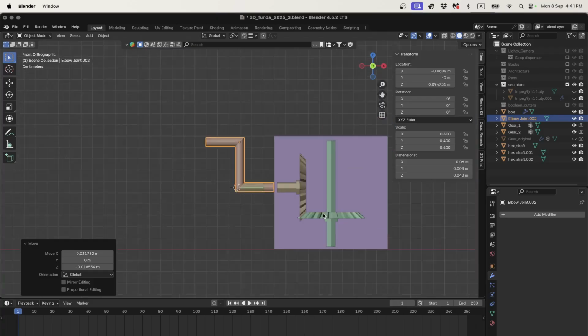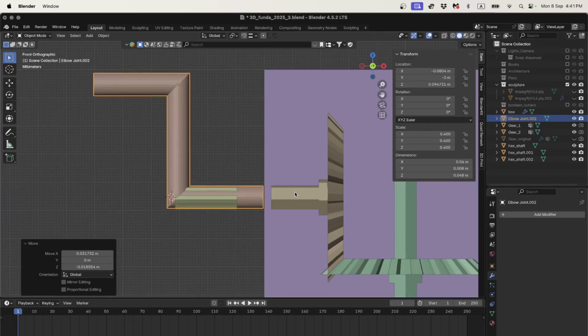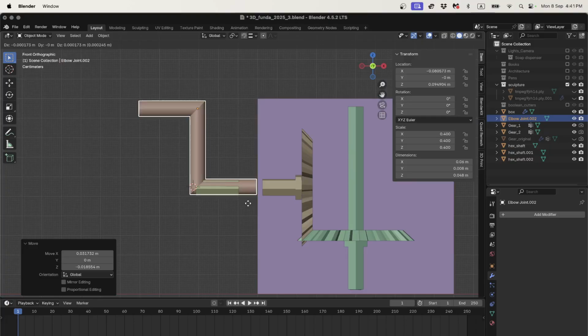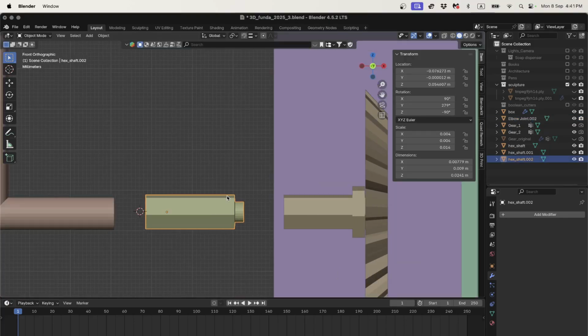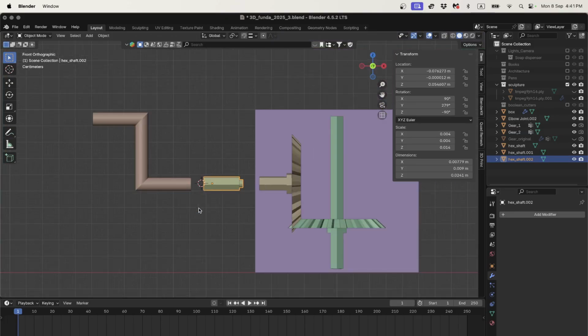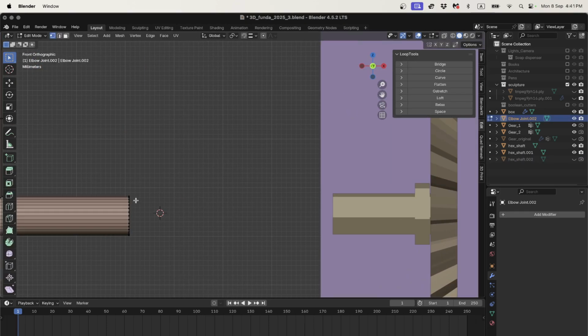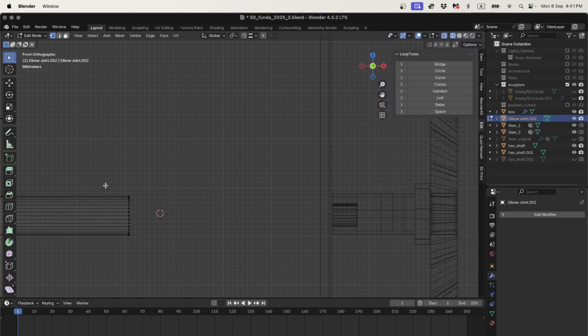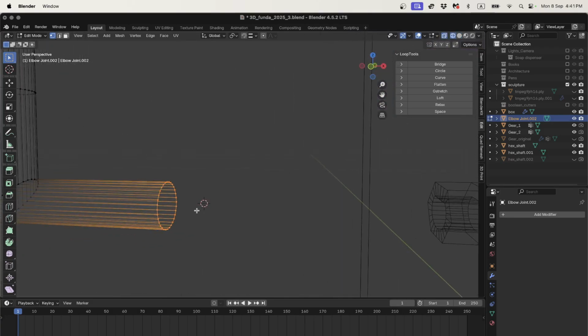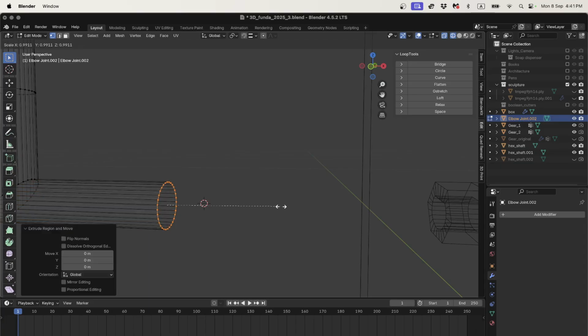So then our crank handle is going to go somewhere like that, but it's going to need that little pin with the D shaft on it to go into the hole there. I think we said our D shaft, our pin, was 5 millimeters high. I'll just move this one for a second. I might hide it. I think we can just make it from this. So I'll go into edit mode, wireframe, grab all my vertexes here, and just as we did before, E for extrude, click, and I'll scale it a little bit so we can see that's where our shaft is going to be.